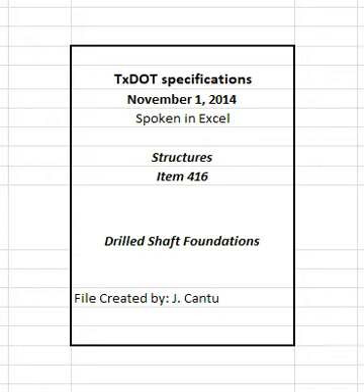3.7 Additional requirements for slurry displacement or underwater concrete placement methods. Place concrete on the same day the shaft is excavated and as soon as possible after all excavation is complete and reinforcing steel is placed. Use an airlift or clean-out bucket of the proper size to clean the bottom of the excavation before placing the reinforcing steel cage and concrete.